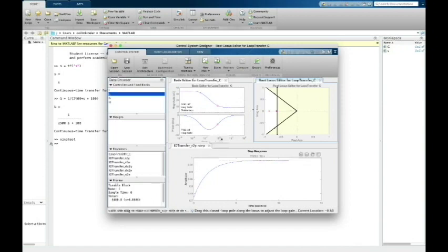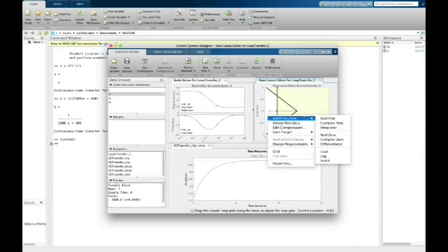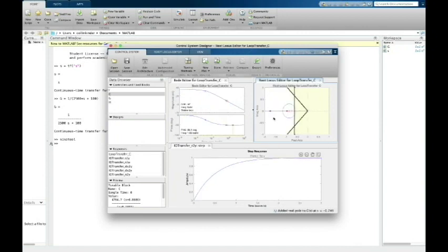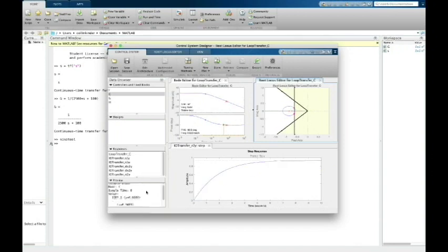At this point, we had implemented a full PID controller in order to regulate our system. This is good because it allows for a more robust tool to work with if this tool were ever used in different vehicles or altered for fully autonomous vehicles. With this PID controller, all of our constraints, rise time, settling time, percent overshoot, steady state error, etc., were all fully satisfied, our closed loop system was stable, and it was fully capable of performing the controls we wanted.